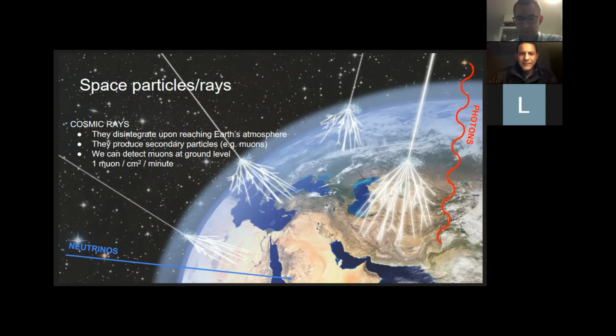The one thing that you need to control very well, because that's a source of false triggering, is light. External photons can be incident on the scintillator and transported to the photosensor, or directly incident on the photosensor surface. So the biggest source of unwanted signals will actually come from photons in the environment. That is why you need to operate the detector in a light-tight environment.